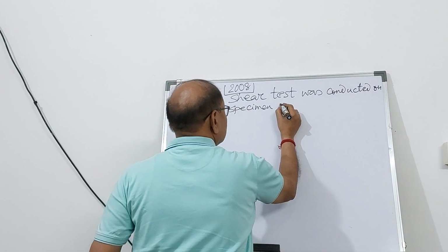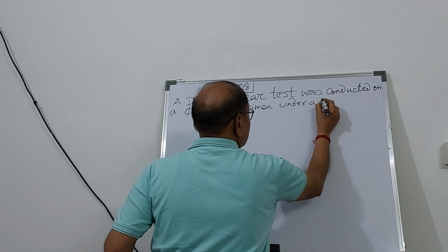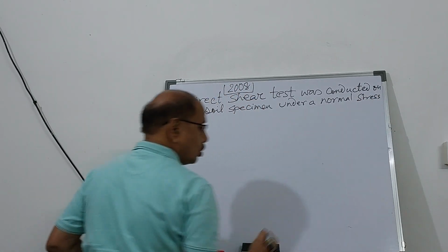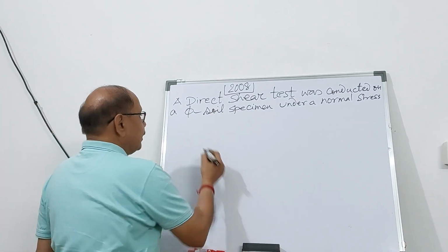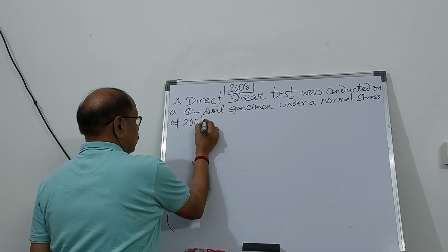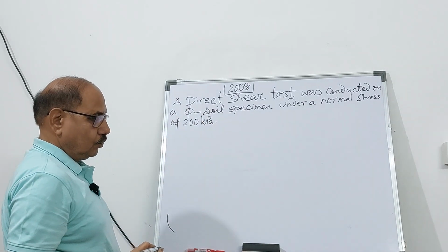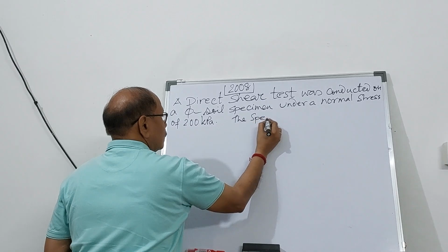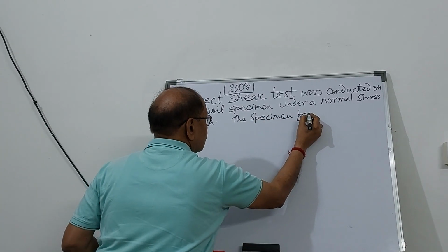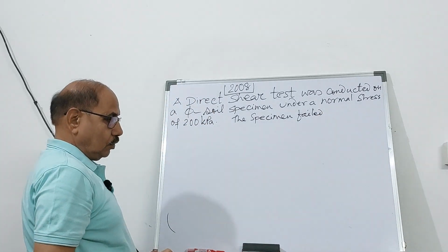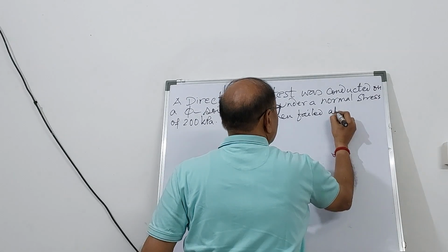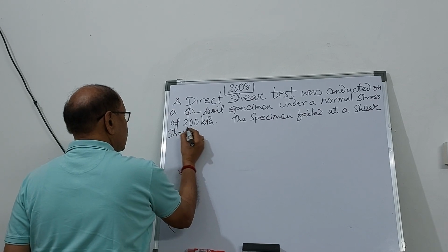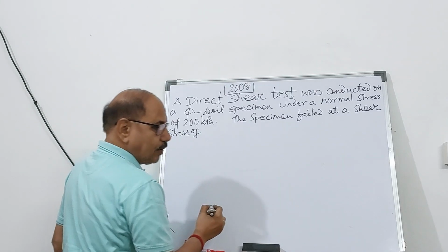Under a normal stress of 200 kilopascal, the specimen failed at a shear stress of 100 kilopascal.